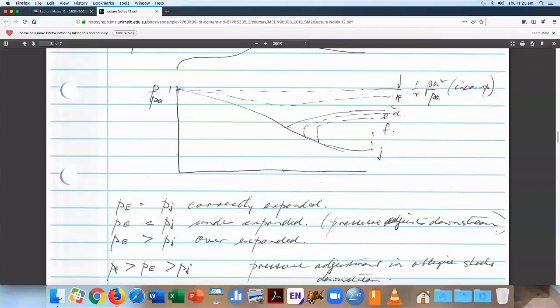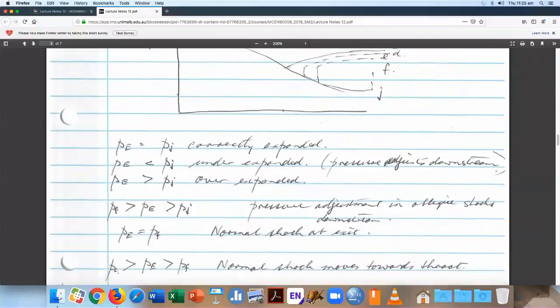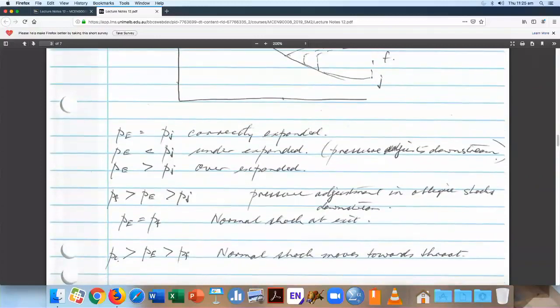Based on the pressure differential, a shock can form in the actual diverging part of the nozzle, right? Yes. So what determines whether or not it will form at some part of the nozzle, or whether it will just continue to expand and then adjust at the exit? Well, once you get something there, you can propagate the pressure field upstream.